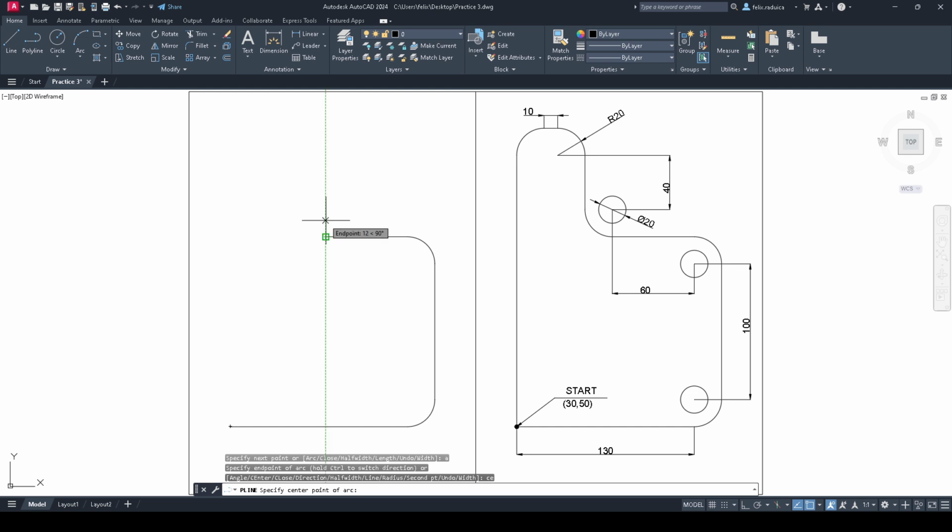Now we have to switch back to the arc, A enter, the arc mode, then center CE, and now the coordinates are upward, so 0,20 enter, and now for the angle A enter, -90 enter, to go like that, and L enter to switch to line mode again, and we have to go upward of 40, so at 0,40 enter.